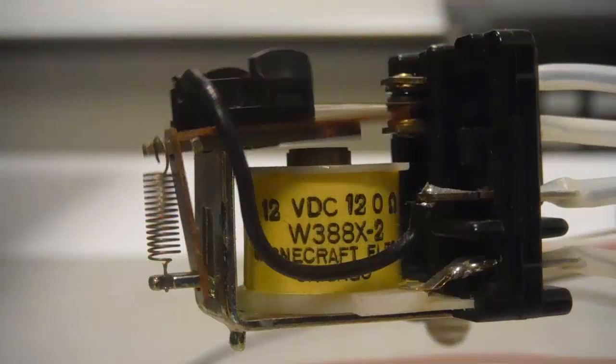2, notice the arcing that is occurring on the contacts. As mentioned previously, a coil contains magnetic energy. When current through it ceases, the magnetic field collapses, propels current in the same direction. This DC coil does not have any means of suppressing this arc. If this buzzer went on for any length of time, we'd damage the contacts.